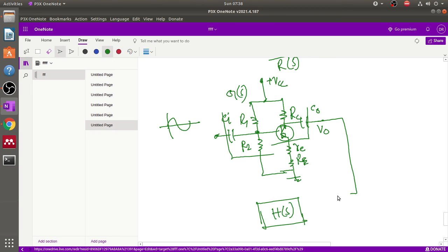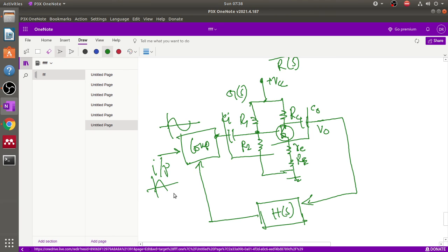Now from here to here we connect our signal, and then this signal goes via a comparator, any comparator. Then we apply here our actual input signal, the sinusoidal signal. So if there is a problem, or if a distortion occurs at the output signal of this amplifier, then via this feedback network we can control our output signal using this error signal at this input ES.